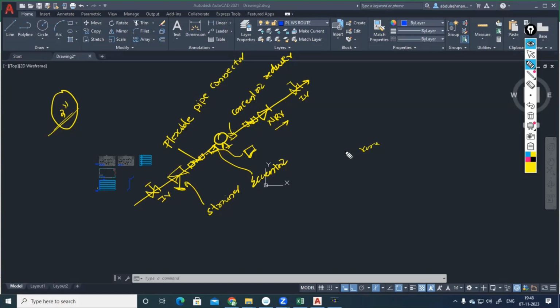That effect is called cavitation. That's why this vortex effect will enhance a process called cavitation. There is another reason as well that we can discuss. So that's why we propose an eccentric reducer on the suction side and a concentric reducer on the delivery side. These are the standard fittings. What all fittings should you consider? These two: isolation valve, strainer and NRV. Other fittings you can neglect.